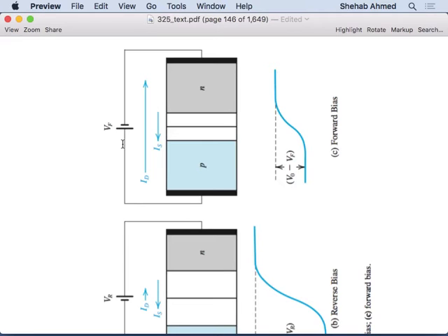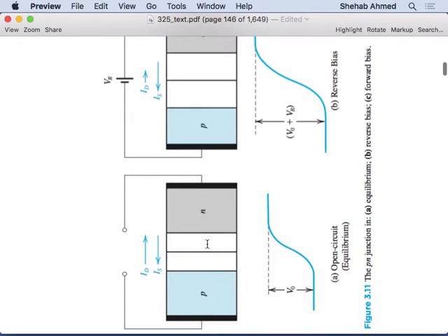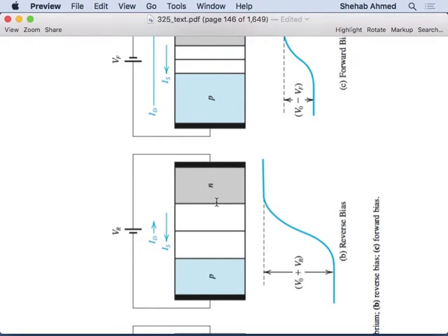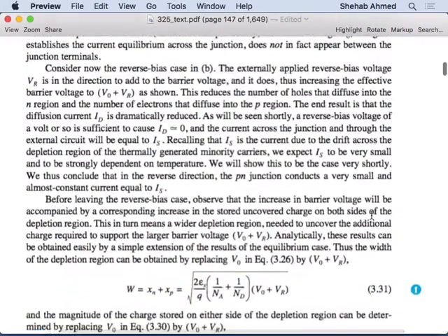This junction voltage is going to range between 0.5 and 0.9. Okay, there will always be. So in all conditions, they showed the depletion layer, but different thicknesses, right? There's always a voltage. Here we have the uncovered charges. Remember the uncovered charges that are creating voltage difference? There will always be a voltage difference, but it will vary depending on whether your device is conducting or not conducting. Okay, so we talked about this.